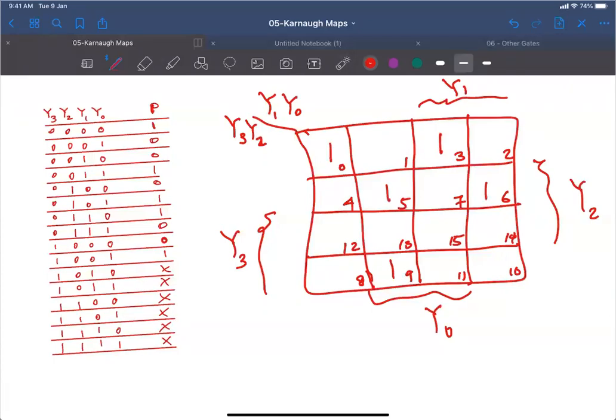The remaining part of the K-map are X's, okay? So from 10 all the way to 15 are all don't cares. So I can pick them however I want, such that my function is as minimum as possible. Notice that if I just choose them to be zeros, can you group any one with any other one? No. So your function will become a sum of minterms, okay?